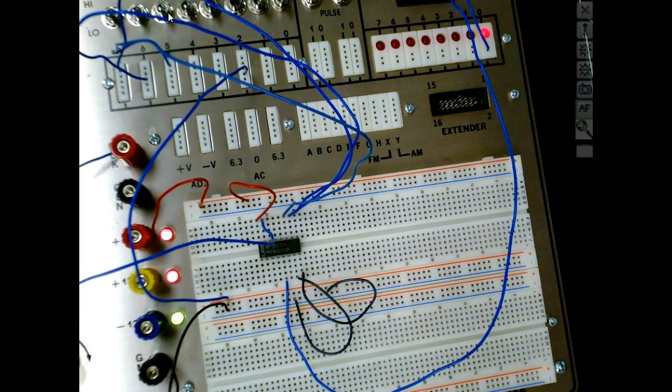When demultiplexing, the A inputs are used as the address data selector. So it wants us to construct this circuit with a 74154. Y'all know what a 74154 looks like? It's a 24-pin decoder. It's a 4 to 16 decoder.